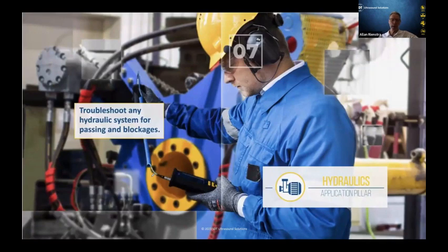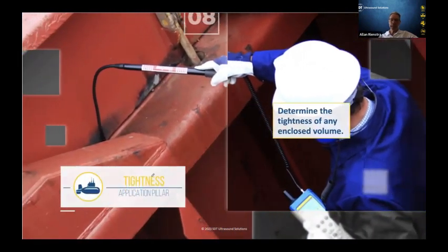I'm also listening for cavitation in the pumps. I'm listening to the bearings on the motors that are driving the pumps that are producing the hydraulic system pressure. And so there are lots of applications for troubleshooting hydraulics. And then finally, tightness testing.